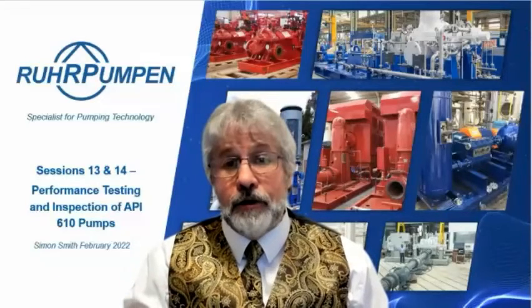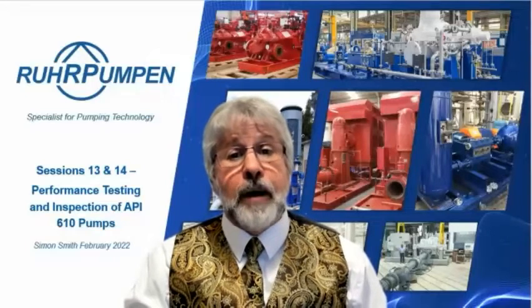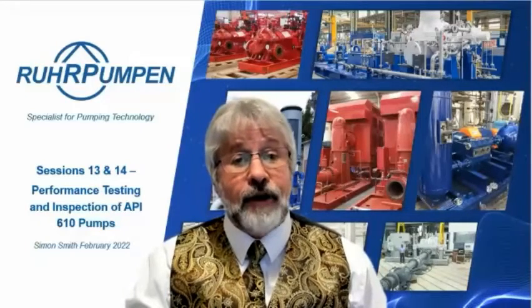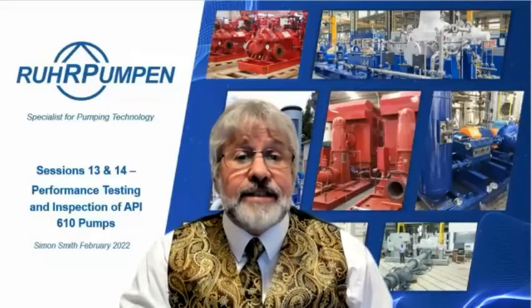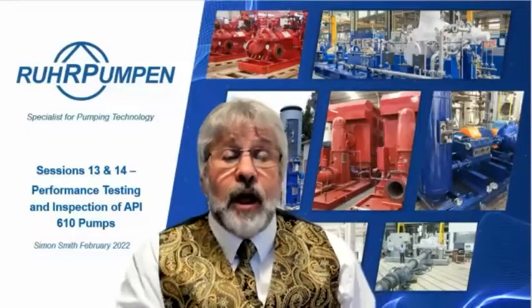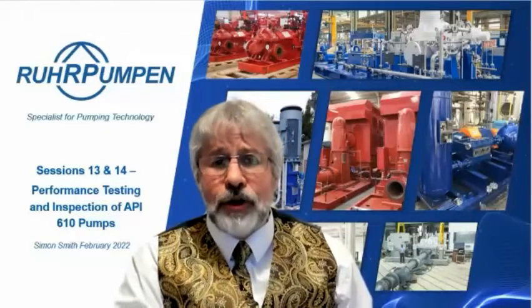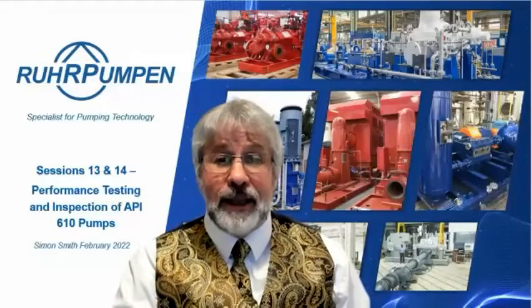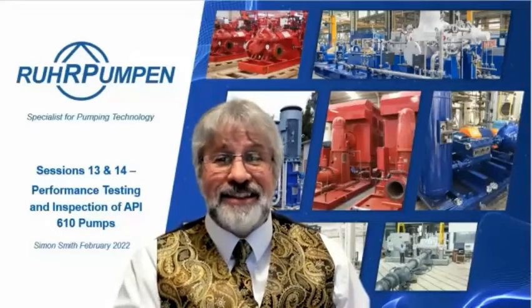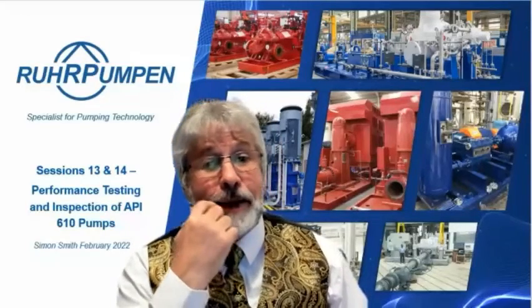The typical requirement from many people is that the pump gives less than 85 dBA at 1 meter. We can test like that, and the figures that we get on a big pump are likely to be more than 85 dBA. But once the pump is installed at site and properly installed and properly tested, it will probably be less than the 85 dBA.